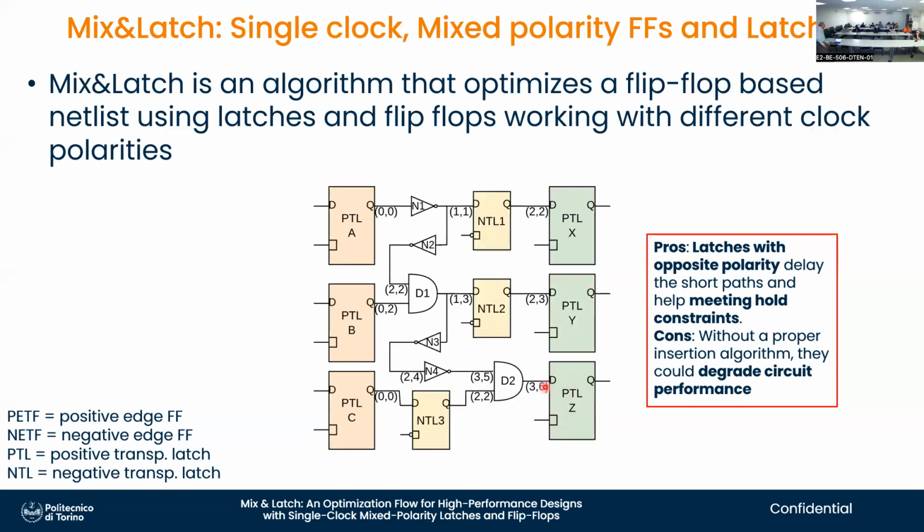However, a very important property that was actually proved by a friend of mine, one of my best friends, when we were back in Berkeley, is that given any circuit with long and short path constraints, there is always a place where you can insert a delay in the short paths that will delay them enough to make them long enough and will not affect the long paths at all. That's the theory. That, of course, is if you can use ideal gates, ideal latches, and so on and so forth. But we will see we can fudge things at the end a little bit to make this hold also in practice.